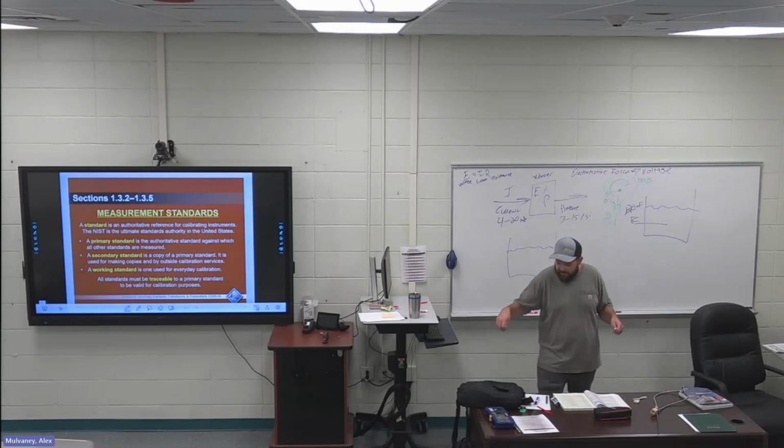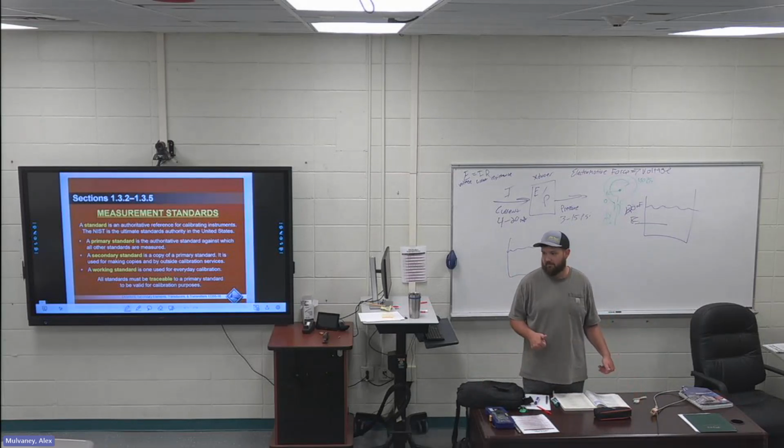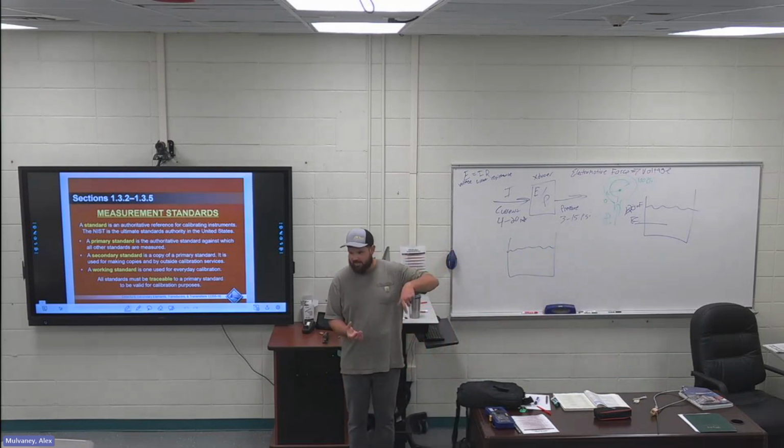But where you can take a tape measure and measure the length of this desk, that's direct. Anytime you have to go from one to the other, it's inferred. Differential pressure transmitter, orifice plate, right? High side is on the front side of that orifice plate, low side.